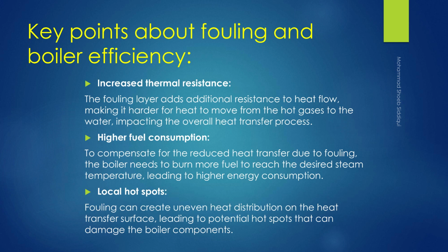Key points about fouling and boiler efficiency. Increased thermal resistance. The fouling layer adds additional resistance to heat flow, making it harder for heat to move from the hot gases to the water, impacting the overall heat transfer process.